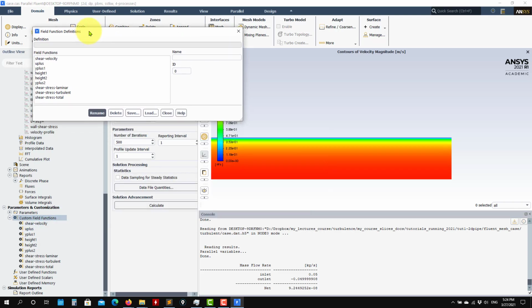So see that, for instance, let me show you the first one, height. So see that here, height, I computed the height, y minus 0.05. But if I use this one, I get negative value because it goes from 0, okay, to the value. So I'm getting negative value. So I need to use absolute value, okay? So you have the functions I will show you. You can access. This is the coordinate. So absolute value of y minus 0.05. So see that this is the normal distance at a point, okay?